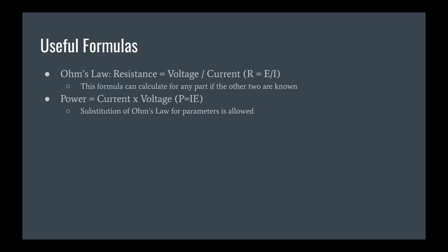And there's a lot of different things you can talk about. You can talk about earth ground, chassis ground, stuff like that. For our purposes, a lot of what we're going to be doing is chassis ground because we are physically working within a chassis, a computer box. The box is a chassis. On your car, the chassis of the car is the ground. So the negative terminal of your battery is actually connected to the car frame. That's why when you jump start a car, you put the positive terminal onto the battery, you put the negative terminal onto some part of the car's chassis. You don't directly put it onto the battery because then you can cause things to explode.